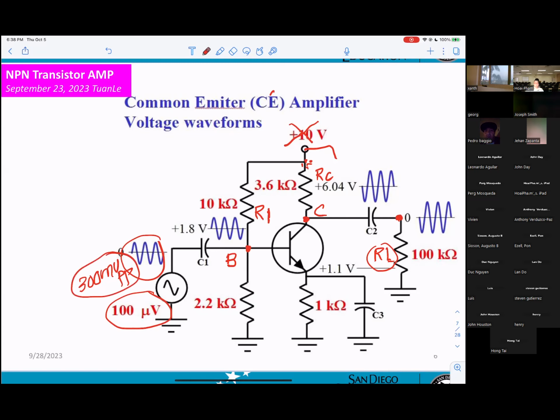What can you do? How do you set up your generator to get a smaller voltage? You have to pay attention to the minus 20 dB button, right? You have to use the minus 20 dB, so you're able to get down to 300 millivolt. That's the only way you can get to that millivolt.